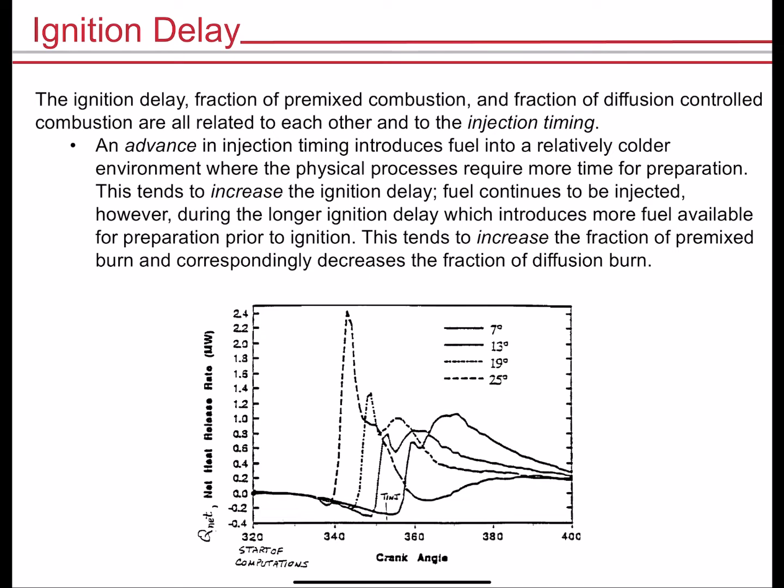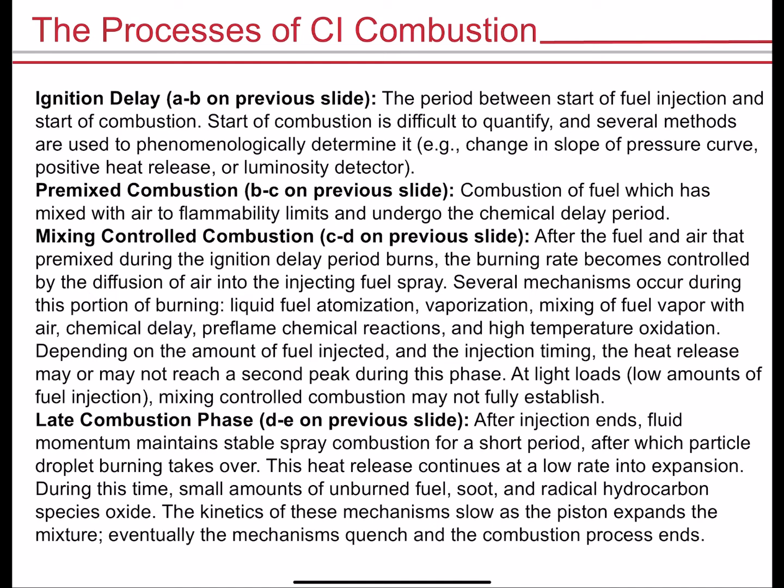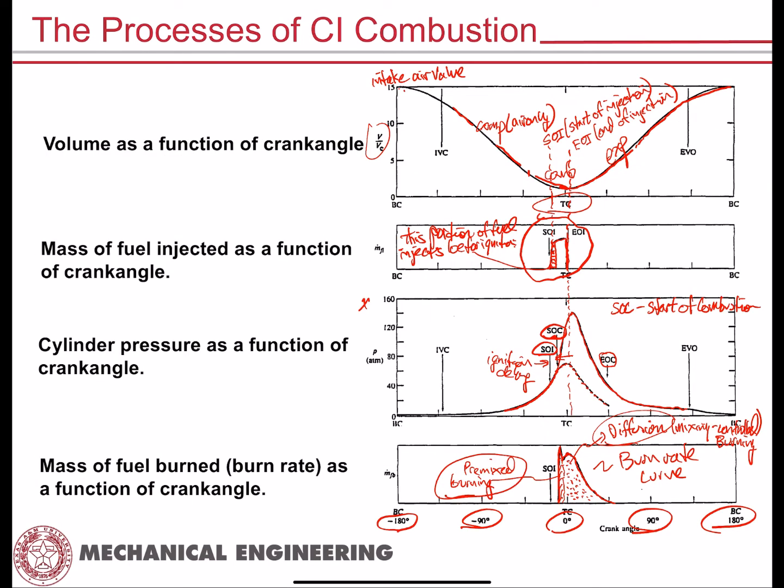And all of these are controlled by the timing at which the fuel gets injected into the cylinder. So if I go back a few slides, remember this slide here where we said that start of injection is here. Well, just like spark advance, we can advance or retard that start of injection. Advancing would be if we were to move start of injection further away from top dead center. And retarding is if we were moving start of injection closer to top dead center, or later in the cycle is a better way to say it, because top dead center becomes a relative way of quantifying advance and retarding.